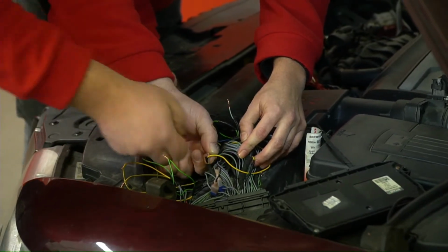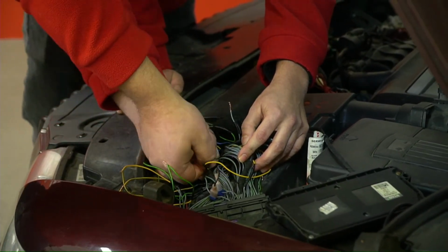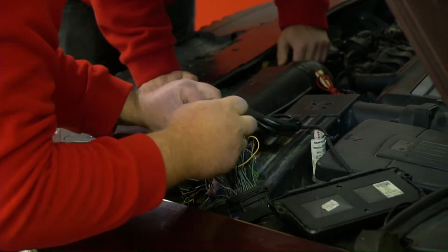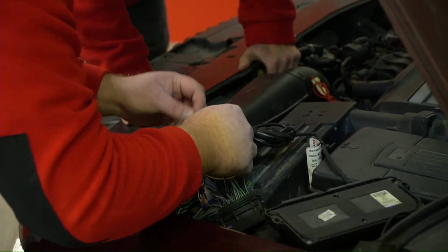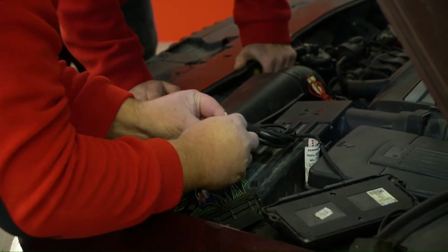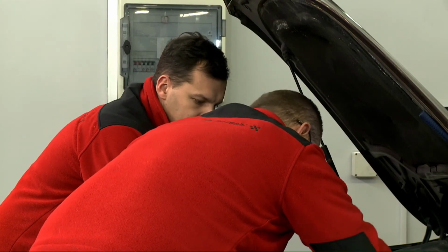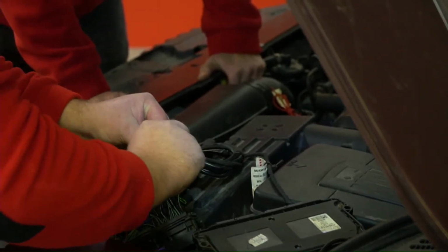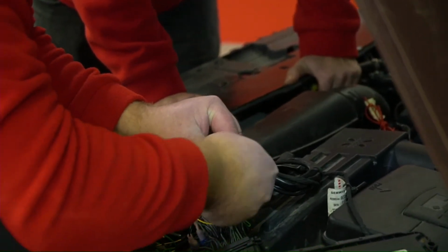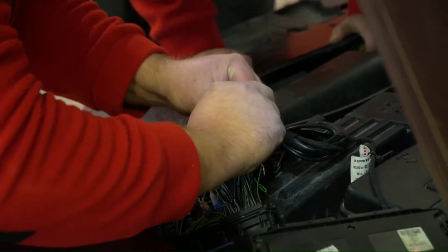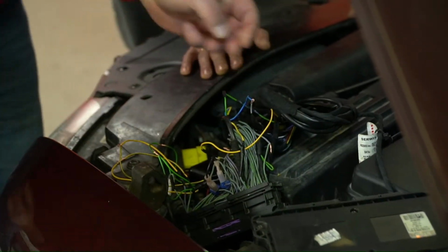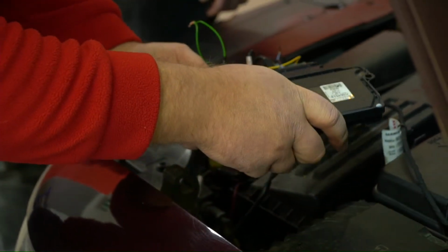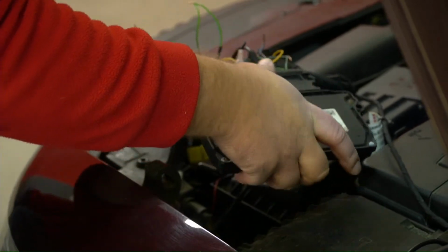Okay, so basically what we are trying to show you is that when you connect to the car and see 5 volts on petrol pressure, it means that something is not okay, not properly connected. You need to check it again and see if the connection was made properly. Because in this case, the gas dosage would be crazy. When our controller is seeing 5 volts of petrol pressure, it will make a very, very rich mixture. It will simply calculate the petrol dosage improperly.